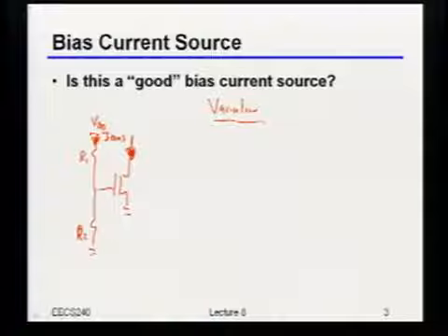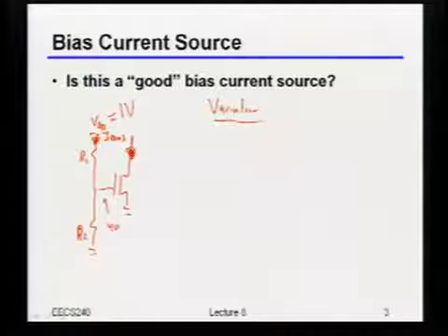Because let's even pretend for a second that I magically give you a great voltage that's always, let's say, 1 volt, right? So even if I did that, and I magically set this ratio, let's say I put this at 400 millivolts, great, I have a precise 400 millivolt voltage. I still claim I have absolutely no idea what the current is. Somebody mentioned it already, but what are the 2 or 3 dominant mechanisms that would mess up the actual current you get, even if you set that voltage precisely? Threshold voltage.